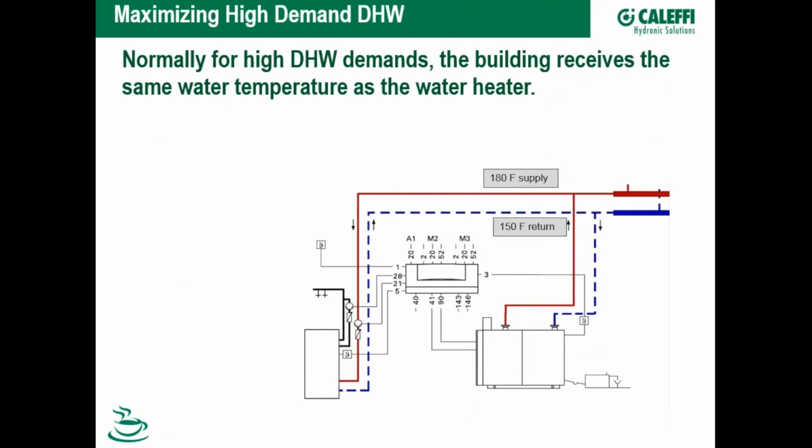There's a wide variety of applications out there where we're putting in an indirect water heater, and the demand for that indirect isn't just about little blocks of time of 10 or 15 minutes. It may be that the call for hot water lasts for an hour, 2 hours, or it may be that the hot water demand occurs for 6 hours a day.